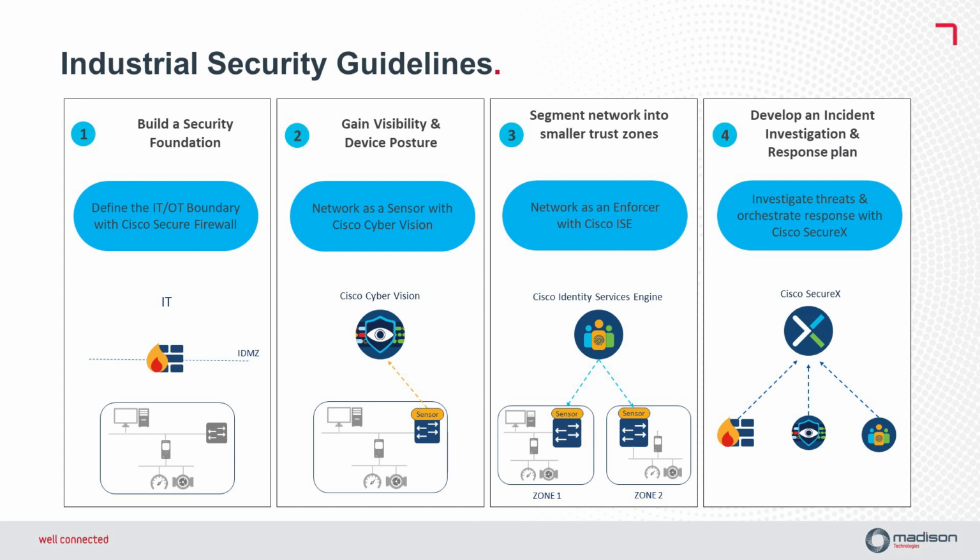Now, Cisco CyberVision is an ideal choice for substation automation for various reasons. It provides you with asset visibility and network segmentation, and after you have developed network segmentation, you need to use Cisco ICE. Cisco ICE can play a crucial role in enhancing substation automation by providing advanced network access control and security features. So access control, device authentication, user authentication, endpoint profiling, and policy enforcement. These are some of the features that make ICE a suitable product for substation automation.